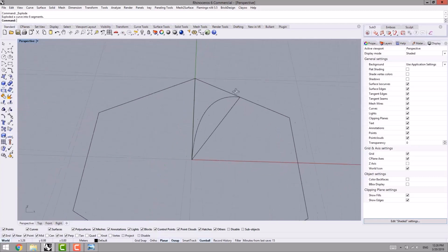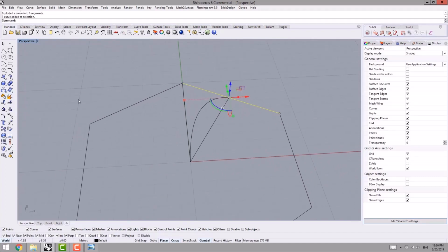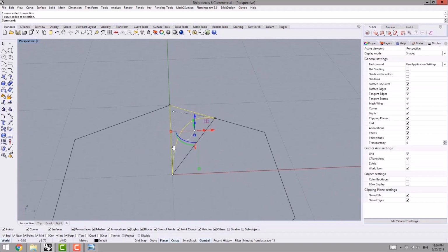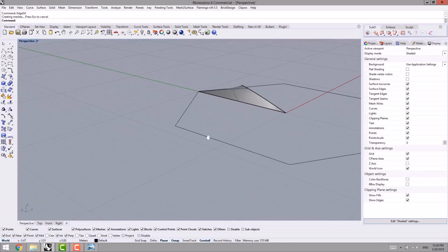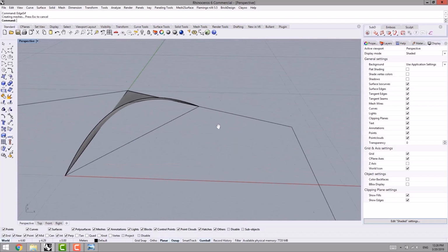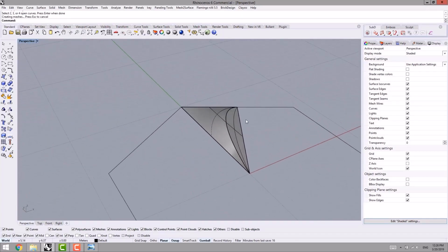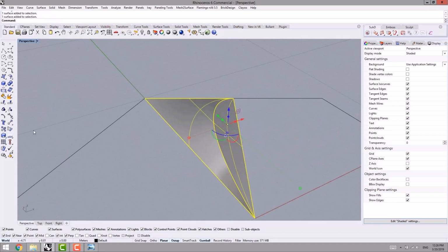Then I select the curve polygon, I explode it, and then by using a split command, by using this line to convert it to 2 single lines, I select these lines in curve, this 3 curve, open curve. I start the command of a surface, and then I create the surface this way. Again, I start the command of a surface by pressing down the space bar. I select these lines and then create the surface this way.